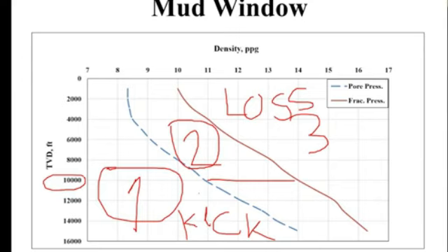Obviously, as you guys may know, we want to be closer to the pore pressure while drilling than to fracture propagation pressure, because the more we move towards fracture propagation pressure, the more overbalanced the wellbore becomes, and it negatively affects our operation. It increases the cost of the operation because the higher the mud weight, the higher the overbalance we become.